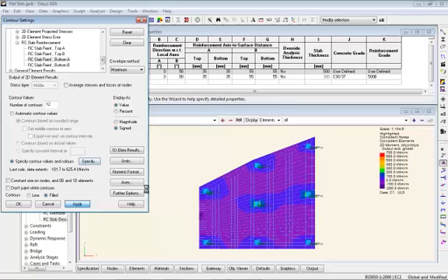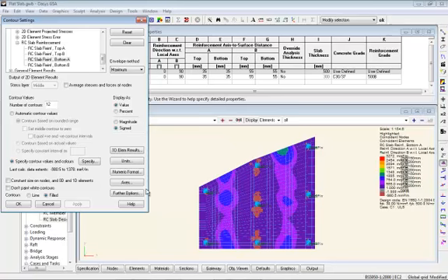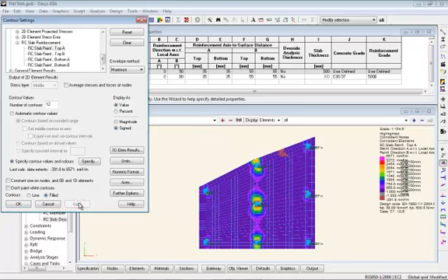So it calculates the reinforcement for each of the elements, and it'll then give us the contours. There we go. And we can see generally the minimum steel, there are some patches in the A direction, which is parallel to X, where we get into compression steel on the bottom of the slab. Look in the other direction, again some compression steel around the columns, and some patches where we need additional reinforcement. Top bars, again, sort of hogging steel, and so on.